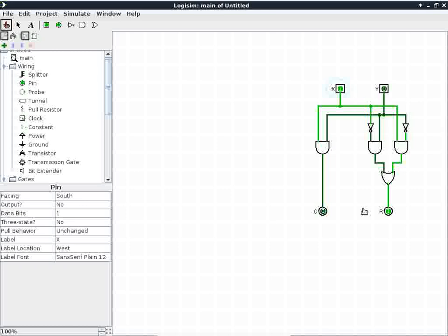Makes perfect sense, right? Let's flip the bits here. So I flip Y to be on, X to be off. Same result. Okay. The output is a 1, and there's no carry. And the last test is to flip both of them on. 1 plus 1 has a result of 0 and a carry of 1. So this sub-circuit is working.